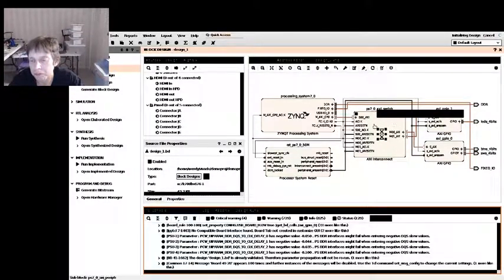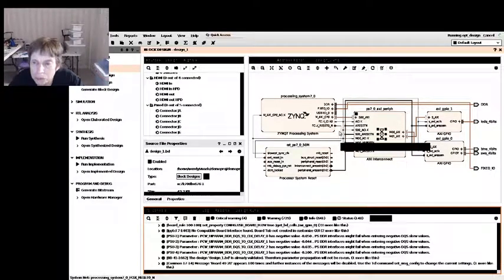And as we mentioned before, this is basically our interconnect. So with this, the purpose of the AXI is to take our input here. This is our input GPIO, our buttons, our switches. Connect that to our processor.